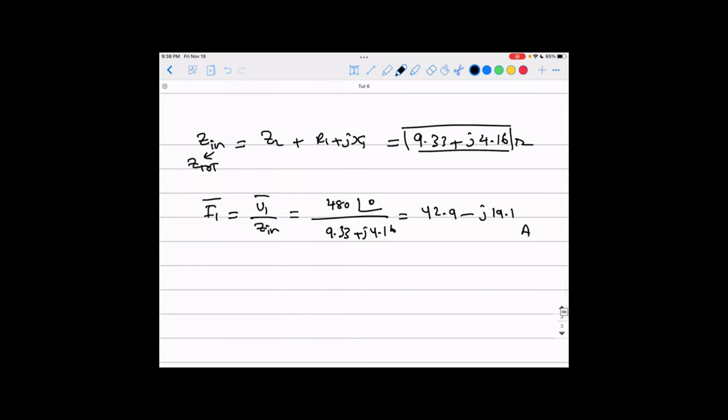That is the phase value. Keep that in mind all the time, phase value. But he wants you to find him I1 line. Okay? And he wants the line current, he wants the magnitude by default. But actually you can find the magnitude and angle, it's up to you. Because that is a delta connection, the line current will equal square root of 3 times the magnitude of the phase current, which is I1 phase, yeah?